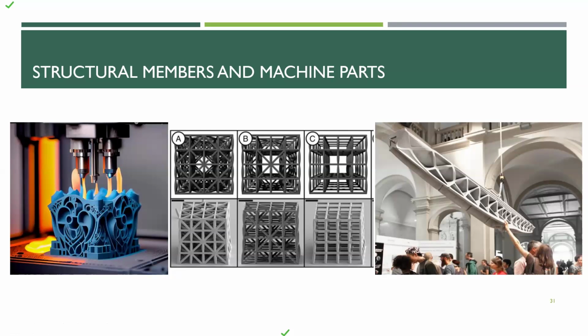So this customization will actually improve the process of structural optimization. Based on finite element analysis and the critical stress points you have, you can put the concrete or steel where you need it, and you can remove the material where you don't need it. So this is also a very important aspect of 3D concrete printing, which not only can make the structure lightweight and safe, but also allows customization, and using FEM analysis, we can use the material only where we need it. We can also use it to prepare prefabricated beams. We don't have to do it on site. We know about modular construction. We just prepare a prefabricated beam in the factory based on the requirement of the structure, and just transfer it to place and then follow.